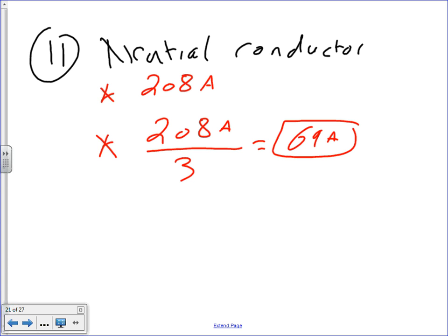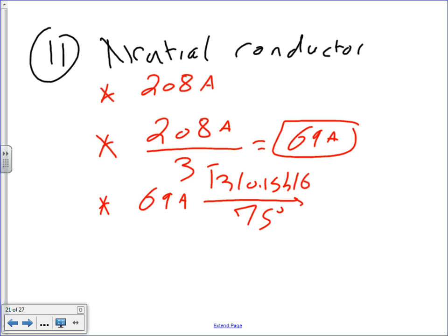And even so, if you take this 69, because we paralleled, now remember when you parallel, take 69 amps. Can anybody size it for me? 310.15 B16 under the 75-degree column because it's a three-phase system. What size under 75? That will be number 4. Number 3 under 75, one conductor, number 3 or 4? Number 4. Okay. Number 4 AWG